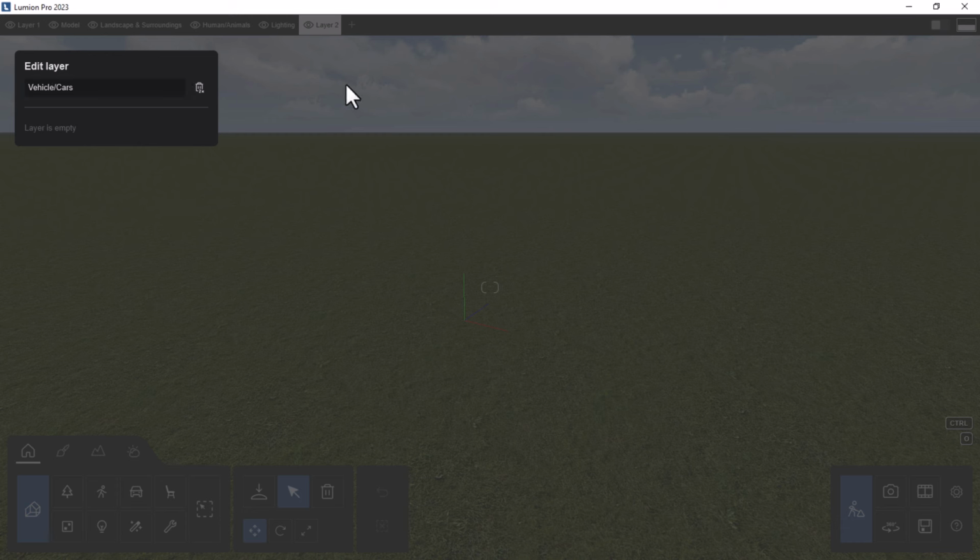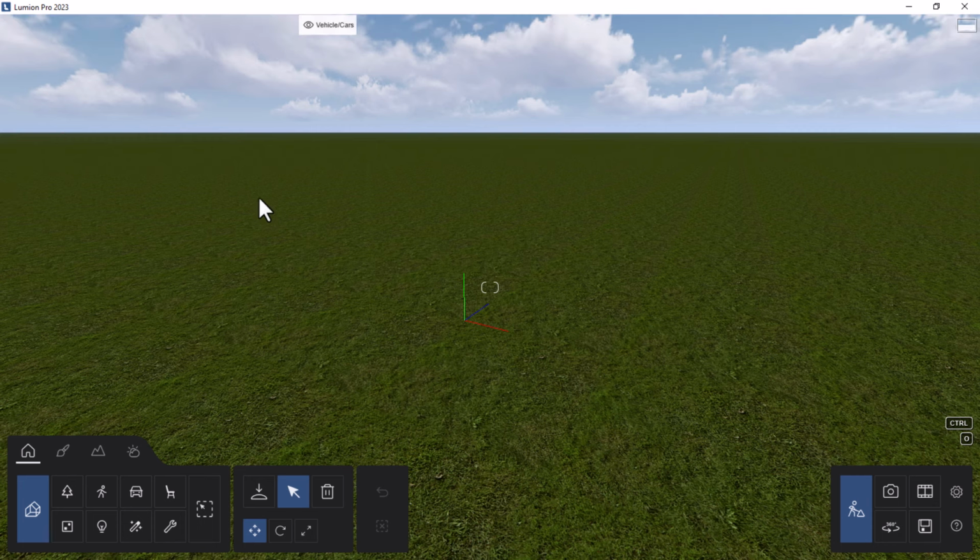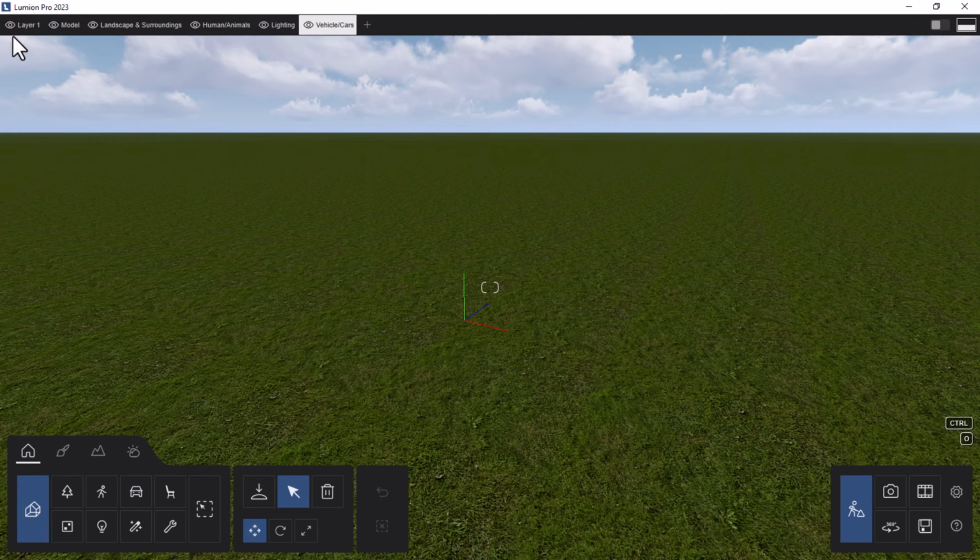Okay, I don't know with the latest version how many layers you could create. I know from Lumion 12 and the downward versions, you can create up to 20 layers. I'm not sure with this one. They're really trying to improve to create more layers in Lumion. So I'll click outside, and I have all my layers now in place.